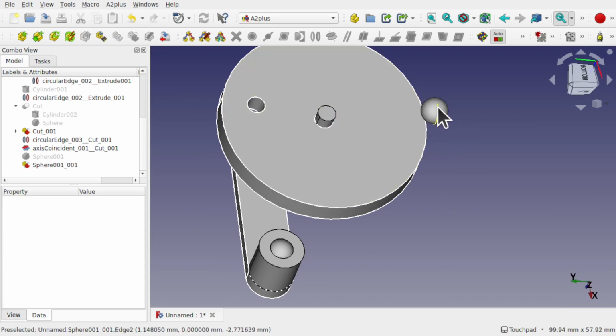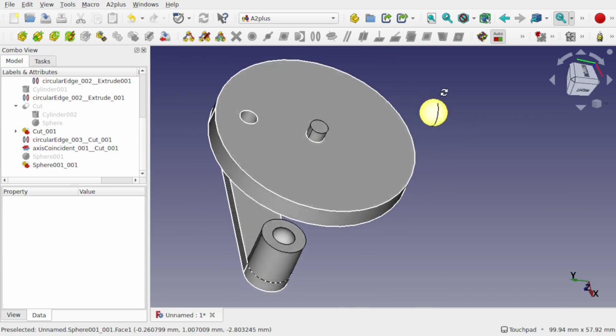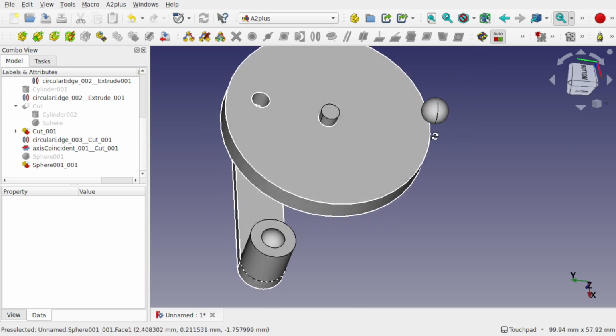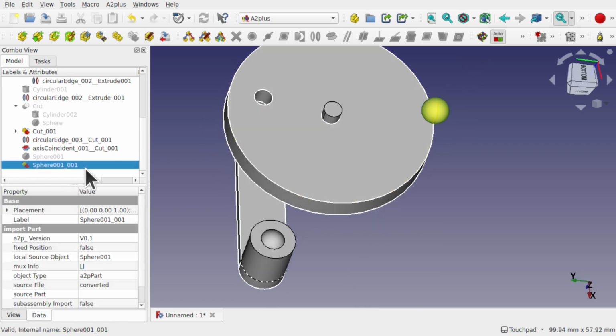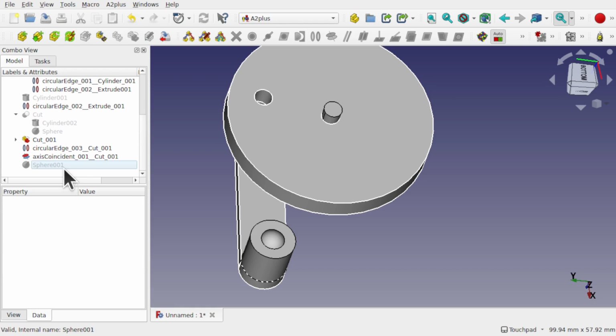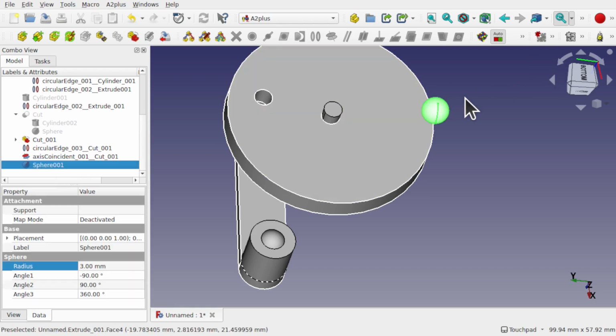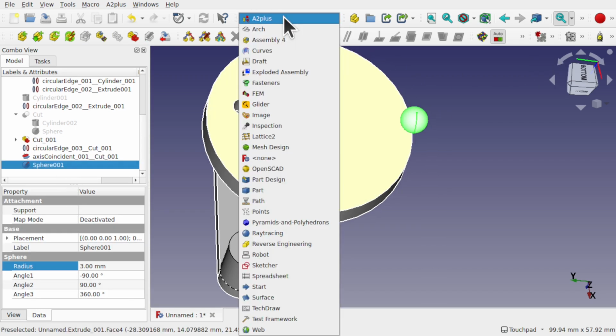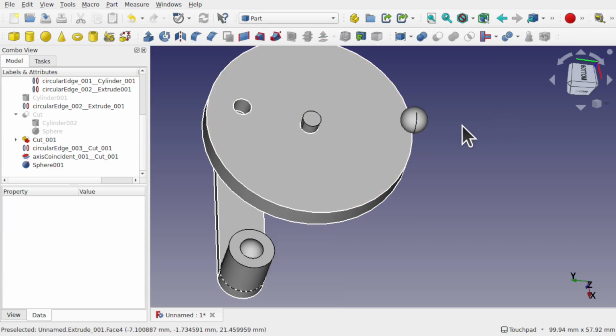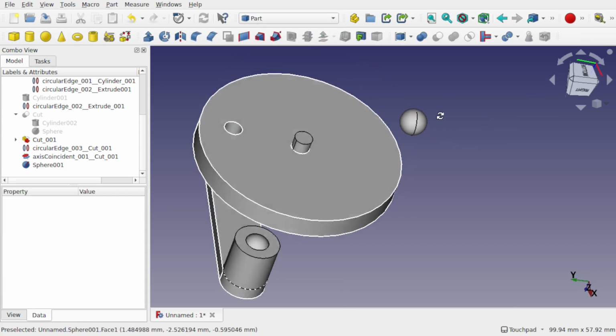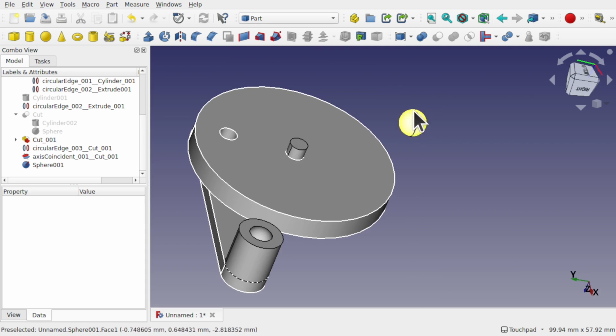This will be now the right size. But I want to update this to have a stem coming out the top. So I'm going to get rid of that original sphere. Let's delete that and bring back the part. Come over to the part, and that's first. Well, I could remove something from here, or I could create this as 2 parts of the assembly, so a sphere with the top cut off and then a cylinder on top.